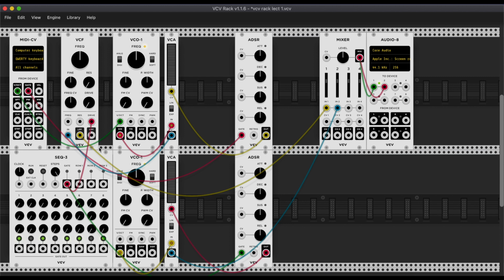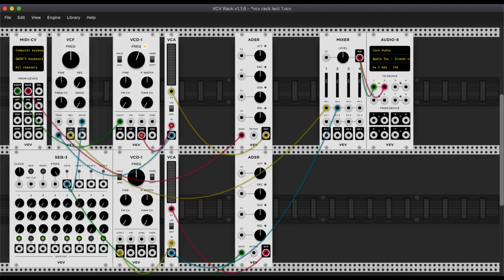Let me adjust the parameters related to the first oscillator so that we can tell the difference from the second oscillator. I change the sound wave to a sawtooth wave, and I adjust the frequency, and I also adjust the filter parameter. Additionally, I add a longer attack and a longer release. And hear how it sounds.